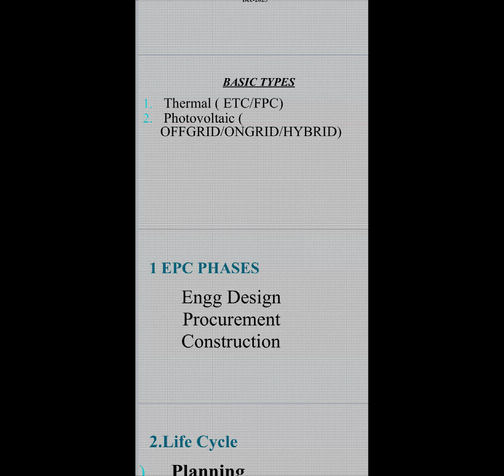Now coming to the second, on-grid system, here there are no batteries. Either the energy is consumed or exported back to the grid. Thereby, you need a net meter system, which is a bidirectional energy meter. So you will get a refund in your electricity bills, whatever energy is exported. And if you have not consumed the energy, but you have exported to the grid, most of the grids, state grids or national grids, they pay you. For example, in Karnataka, you get 3 rupees 54 paisa per each energy unit you generate and sell to the government,